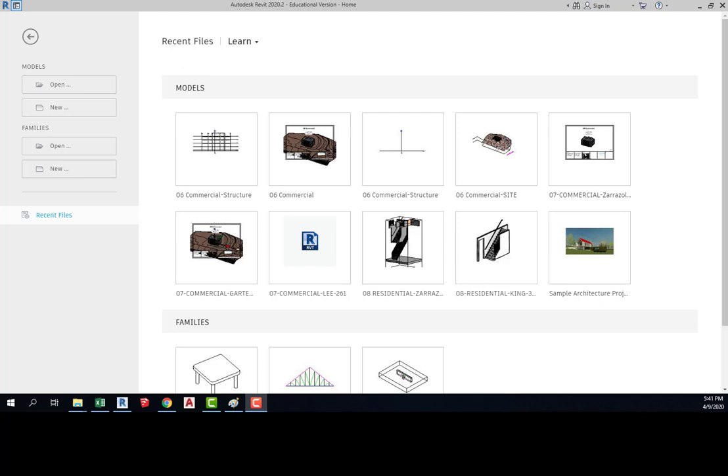The next part of this exercise, in the very end of chapter 7, is to introduce a concept where we copy monitor elements. So these are pieces of linked files that alert the link that the original file has been changed and that they no longer match the conditions. This is super important when you're thinking about trying to create a condition where the various components of a federated model are altered by different parties at all times.